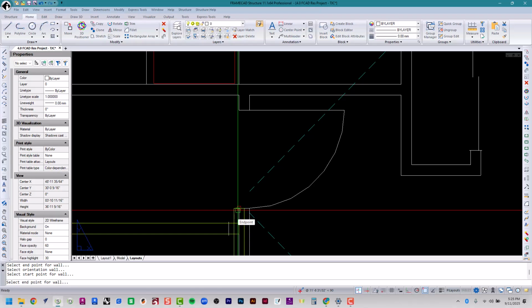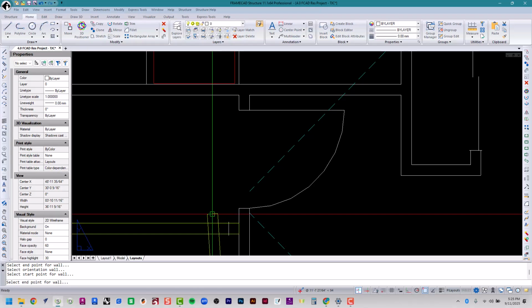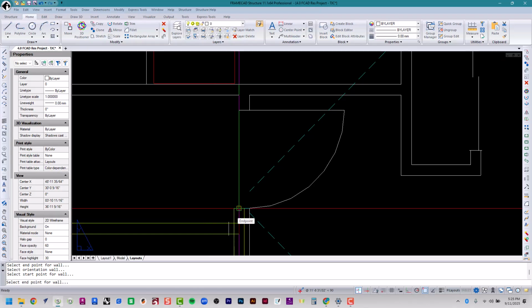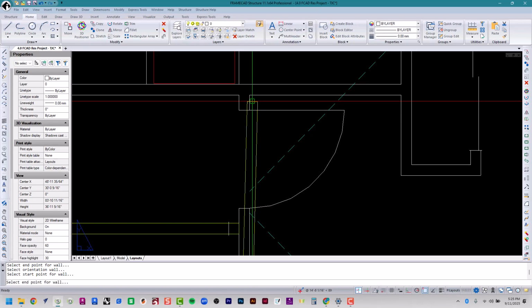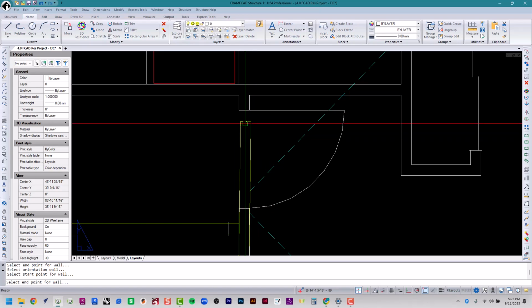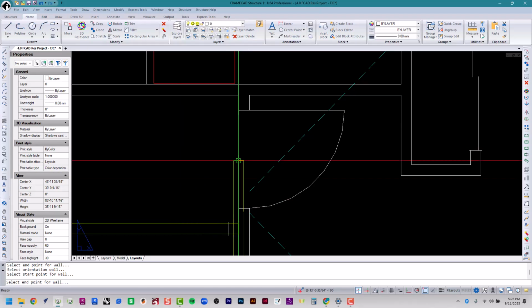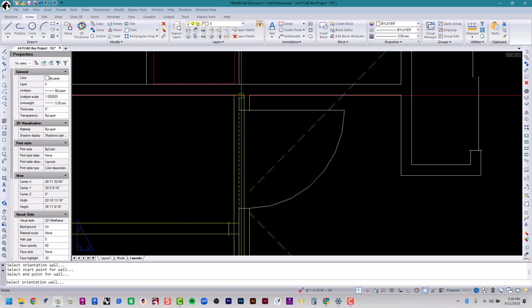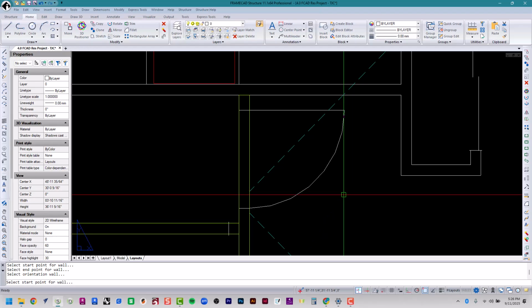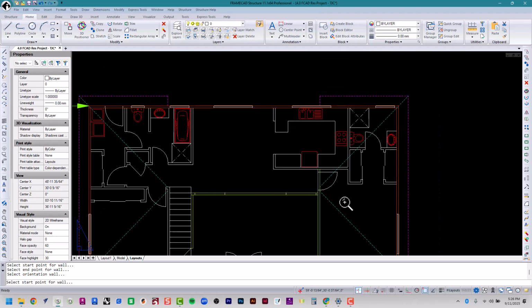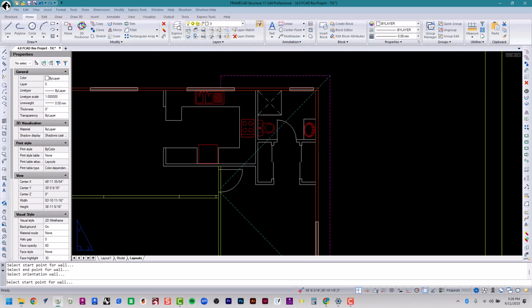A door is an opening through the wall, but a door is not considered by a wall ending here and then another wall starting over there. There is usually wall above this door opening. So don't end the wall here, end it way over here. Click there, click this way, there's another wall. Just keep going until you've got all your internal walls.